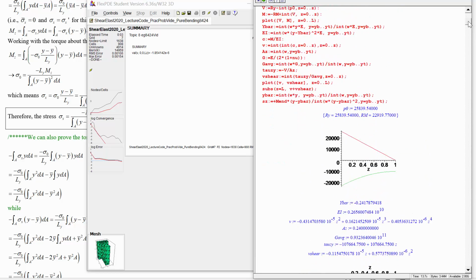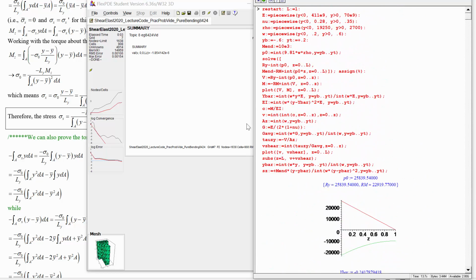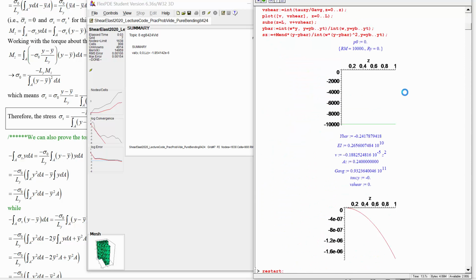How could we compare that with what we're getting in Maple? Well, one way is to mess up the Maple simulation so that it is no longer including the weight. How do we do that? Well, we can set gravity to 0 and see how different it is.